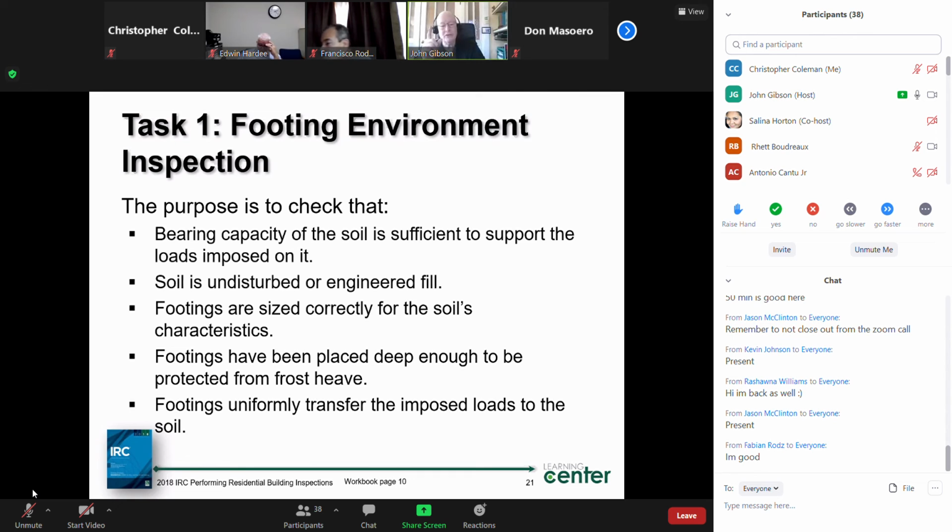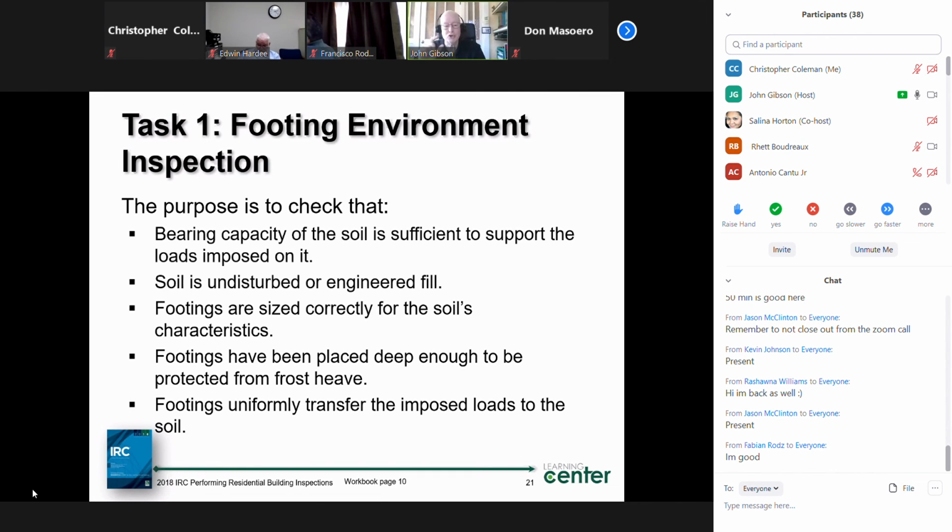Now there's one other measurement that could also trigger that basement being a story above grade plane. And this one says from the first floor, the floor above the floor in question, I go down until I hit finished ground. It doesn't say the grade plane here. It's talking about finished ground. And it says if you are 12 feet or more, then that is going to be considered a story above grade plane.